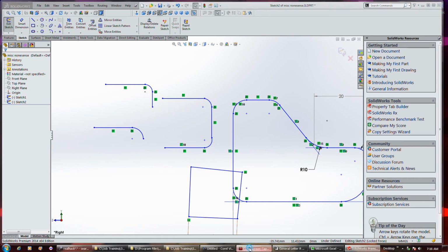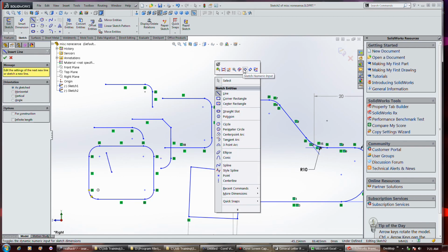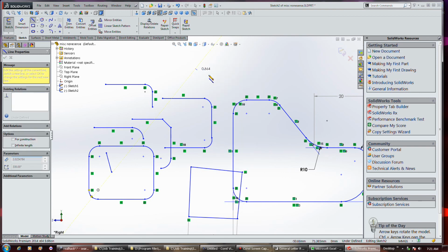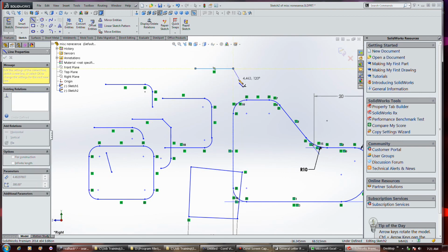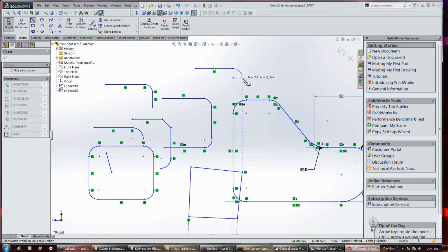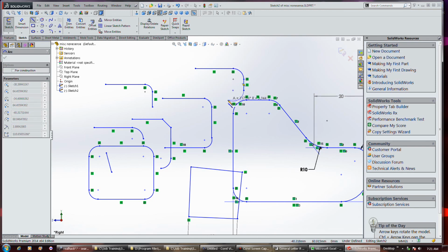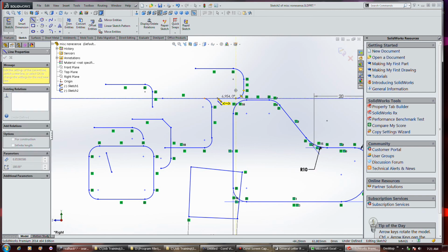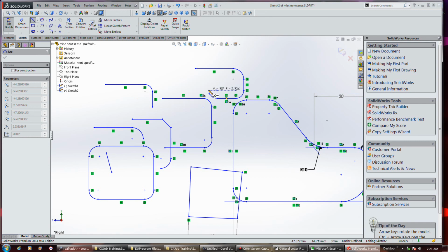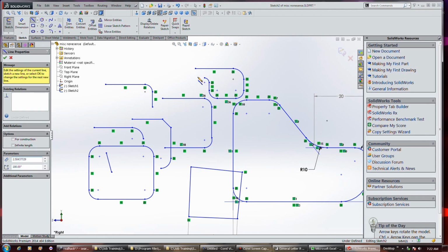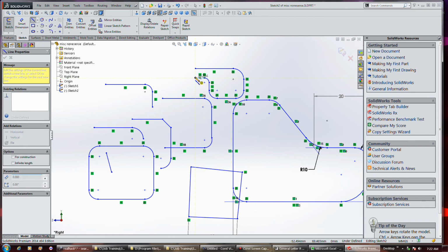Now again, one reason you may want to turn your numeric input off is if you really do want to use that stupid arc function, it makes it a lot easier just by typing A to switch to arc mode. Because you can actually switch between it rather dynamically. But again, Solid Edge, I think, did a much better job of implementing this than these guys. Anyway,